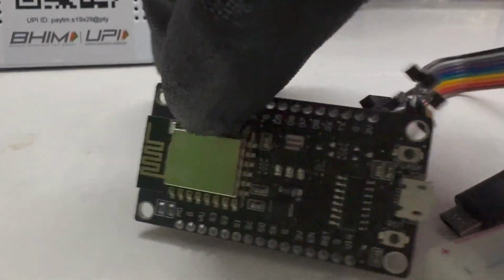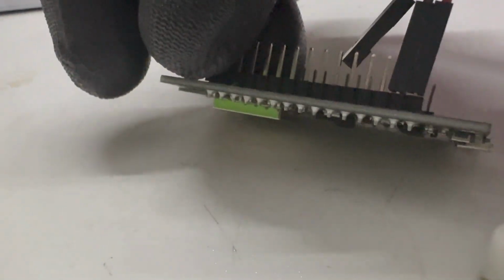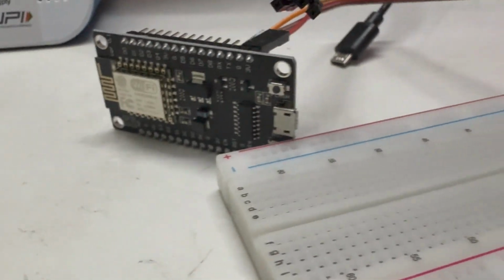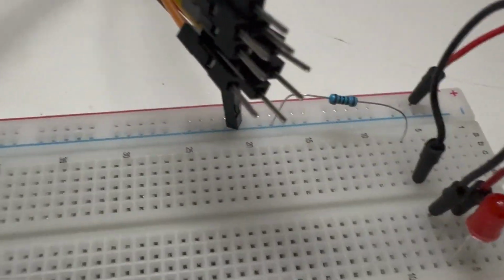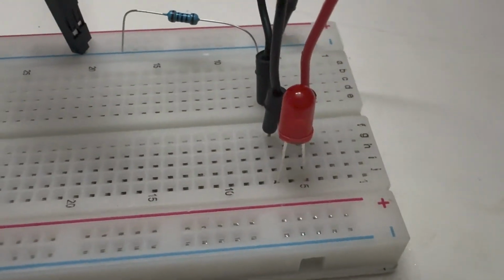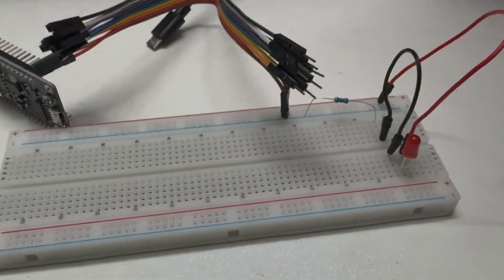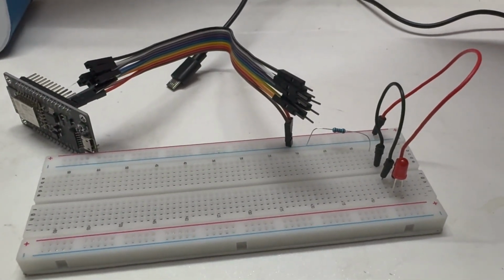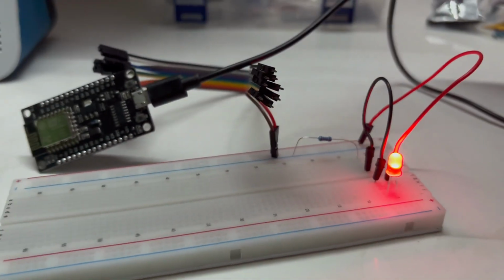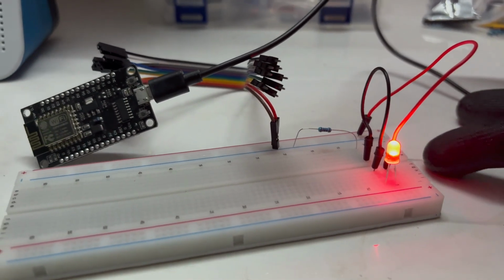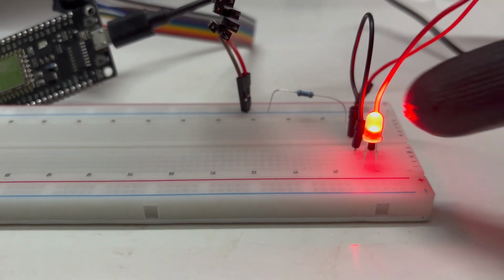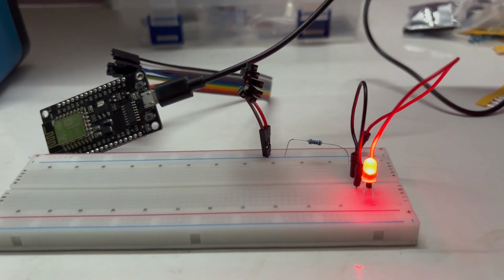What I have done is I have basically connected the 3 volt as the positive and ground as the negative. The connection is pretty simple. Just connect the resistor and the LED in series. Make sure that the current first flows to the resistor and then to the LED, thus preventing any short circuit. If you have done everything correctly, you will notice that the LED starts lighting. In case there is a problem and the LED does not turn on, I would recommend you to flip the LED because you might have connected anode and cathode wrong.